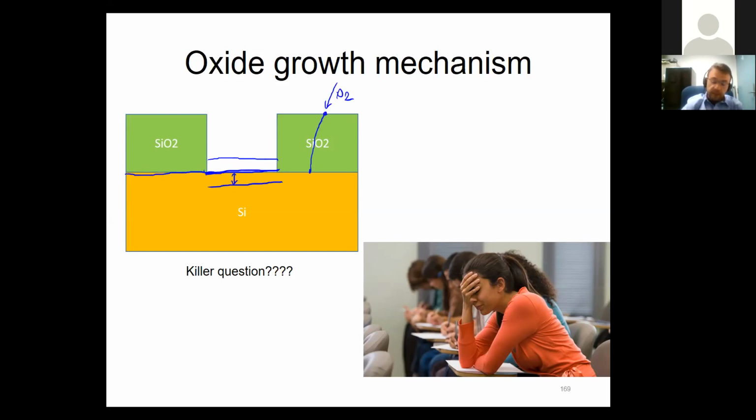So that makes this process on the sidewalls slower than the process here, because here it just sees the bare silicon and it can grow the oxide much quicker. So this is quick. What I'm trying to say is the total thickness that I will grow will be thicker here compared to the total thickness that I will grow on the other portions. So meaning that I will not be able to eat away that much of silicon here. So it's going to be higher. So you see, the levels are not going to be the same. So it's going to be a little higher.